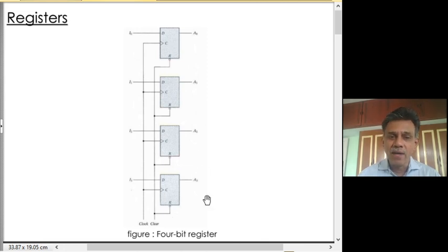Well, you may have a requirement to store the data into this register only at a certain point of time. Typically when the previous stage connected to this register has computed some result, and that result is what you want to store. So you don't want the storage to happen in every clock period, only at certain clock periods. In this case, what do you do? You might say, well, whenever I want to store, I will give a clock pulse. Other times I don't give the clock pulse. Well, that is the right way.